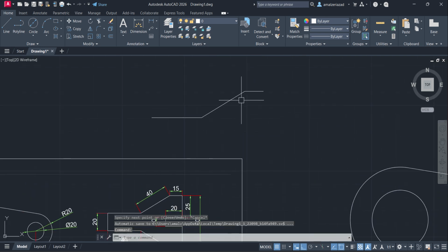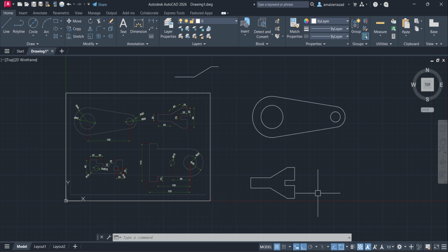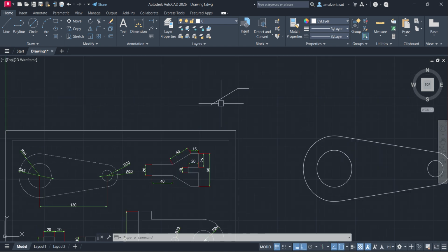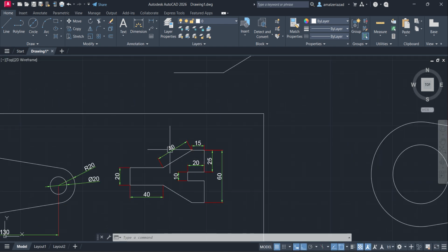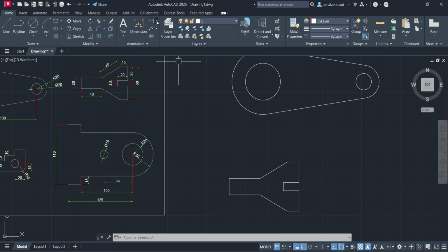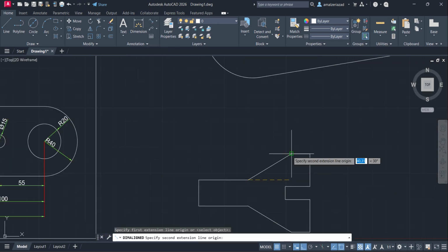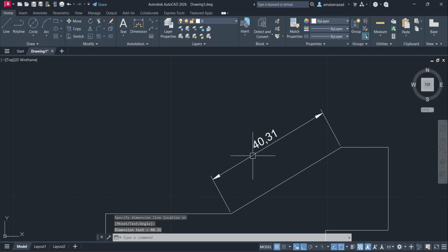Like this also you can be able to do. Otherwise, you assume the complete angle and you draw it like this. Both the things are acceptable. And more than this, if you do something like this, that will be even better. Why? Because this aligned dimension also we have to maintain. If I go and check this one, most probably it might be correct or else it might not be also. You can see the aligned dimension is somewhat like 0.31.